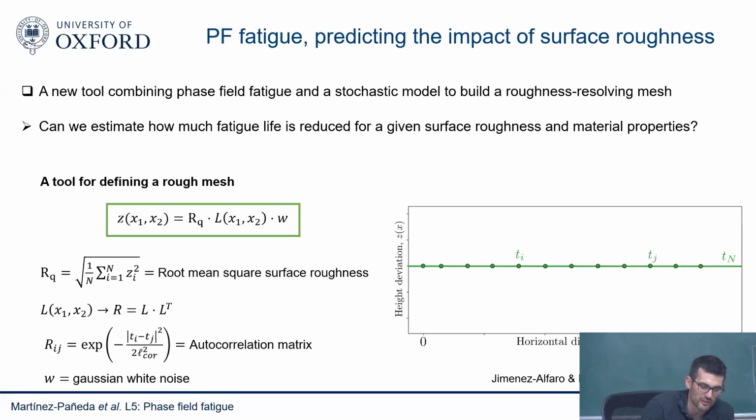So people normally quantify roughness using a couple of parameters, typically 2. There's this Rq, which can be related to another one called Ra, and this correlation length. These are the 2 parameters. So this will be the case, for example, of a perfect surface. You have basically a quantity that is the normal to the surface, so it will give you how much roughness of the surface you have. It's a bit like white noise. Some people have been working with these things in imaging techniques, in optics and so on, to come up with rough surfaces.